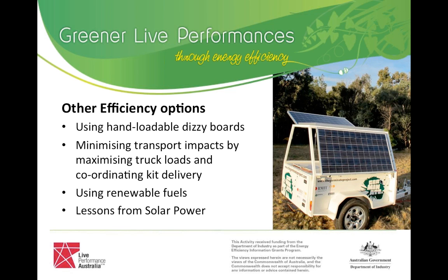And so could you opt in on the discussion around the wasted energy opportunity? If you've got one of these larger generators on, we know that they're going to use more fuel per kilowatt hour. But if you're not drawing down that power, so you are starting to come down into the 50, 40, 30% range of its actual potential output, are you just wasting fuel?